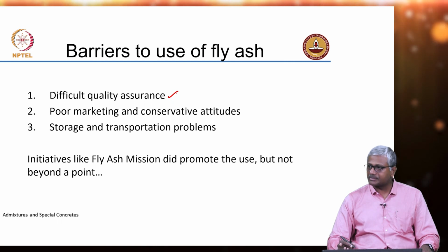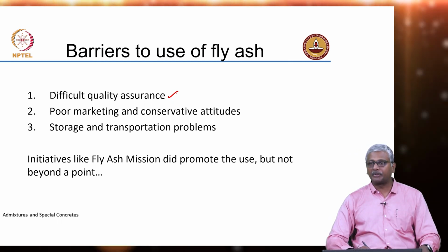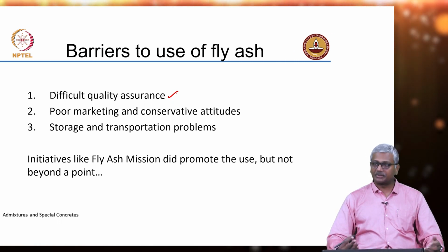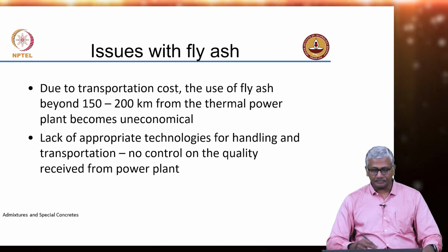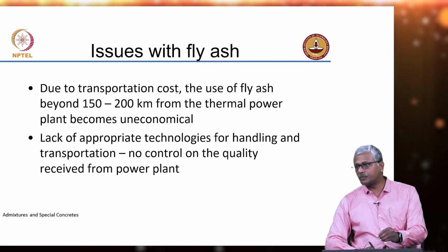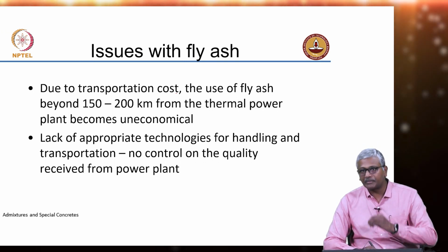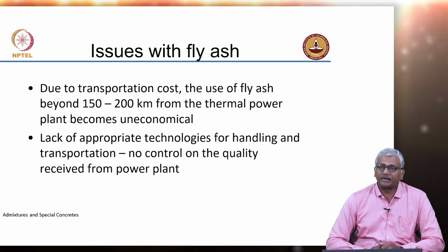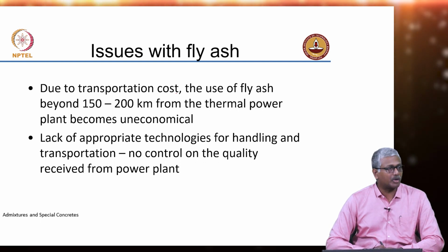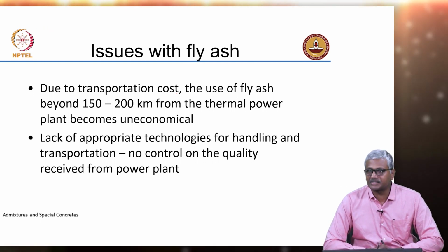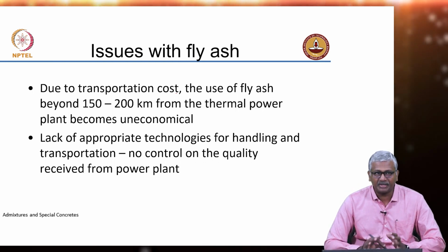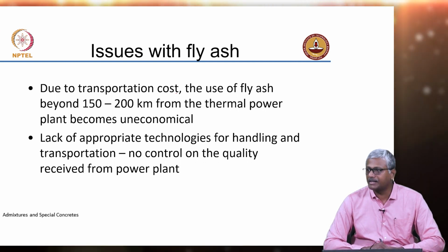So, blended cementitious systems with fly ash are probably a lot more popular, because you know for the residential market you can only get PPC these days. So, fly ash is consumed significantly in making PPC. The other aspect is fly ash has to be available close to where you are making concrete if it is to become economical. If your distance is more than 100 or 200 kilometers, even if fly ash is going to improve the quality of your concrete, its use will be unjustified, because it is going to increase the cost of your concrete.